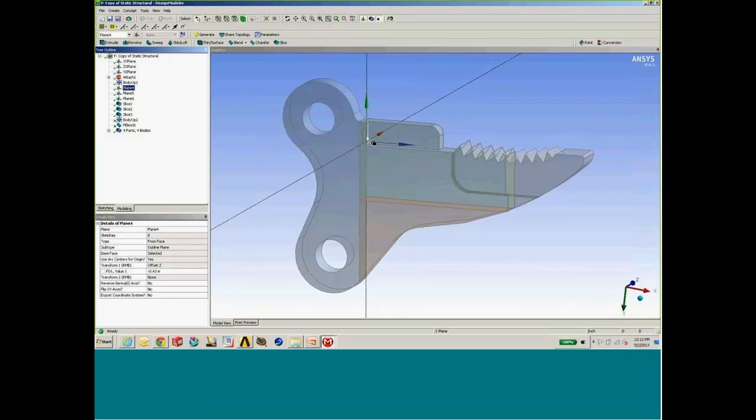If they're not, just simply parametrically modify that model by changing the offset value that I'm using for my plane and hit the update button or the refresh button to just recreate the submodel solution. So essentially with setting one parameter value and one button at the top of the screen, I can very easily just refresh my submodel solution and gain confidence that my boundaries are in the right location or in adequate locations.